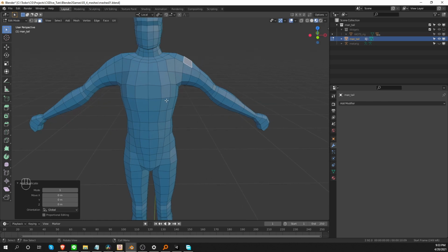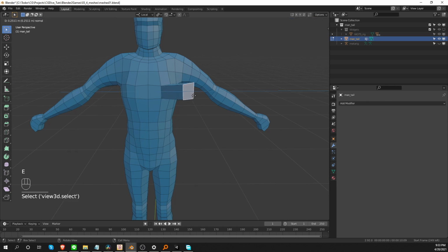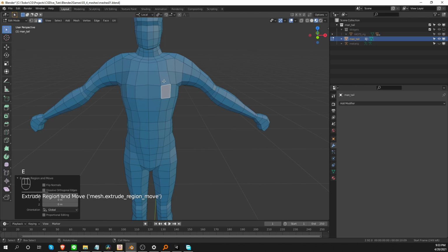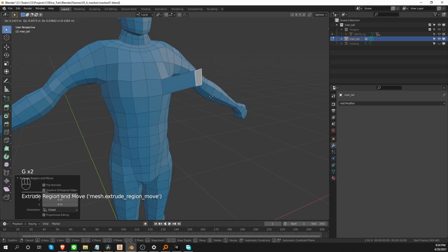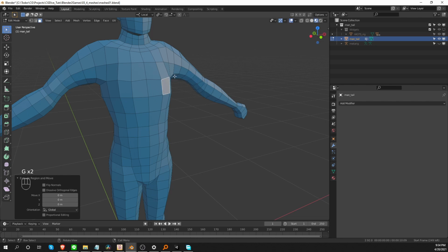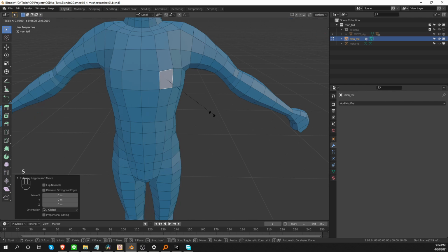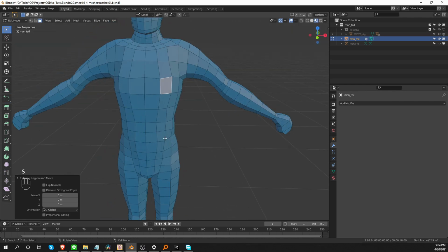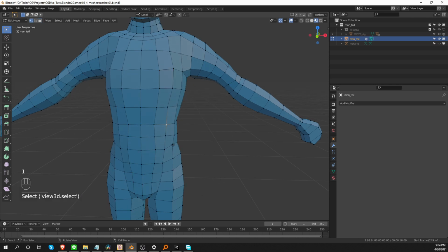one overlapping geometry. Something very similar happens if I select another polygon and press E to extrude, and again I decide I don't want to extrude, and right click. Again, it may seem like nothing happened, but really the new geometry is there. It's just collapsed at the location of the original polygon, and so it is not immediately visible, but it is there. Something else that you can do by accident is if you have a vertex selected and press V, you may want to press B for box select, but instead you press V, and that rips the vertex and creates a hole in the mesh.